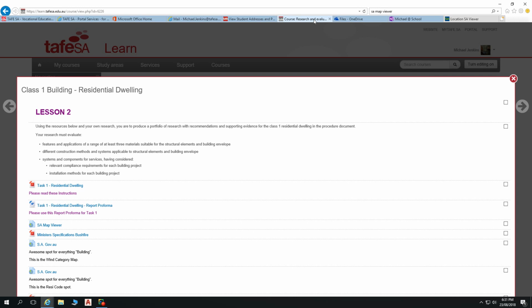If you're wanting to find some things to talk about compatibility and interaction between elements, you can say, if we were to go with a cladding system that is part brick veneer, part this, we've got to have control joints. We've got to think about differential weight on the footing system, all that sort of thing, if you wish. But you can also just make it very simple for yourself and be specific to those techniques.